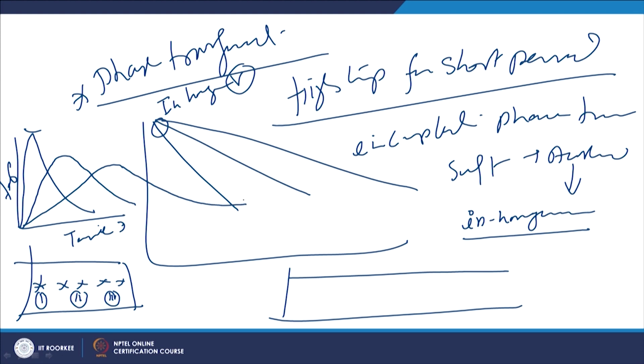So, this slope indicates the cooling rate being experienced, and the slope during the heating indicates the heating rate, and above a particular temperature line, it will be indicating how long high temperature is being retained, for how long period the temperature above that value is being retained, and that will be governing the kind of homogeneity or heterogeneity that will exist in the austenite.